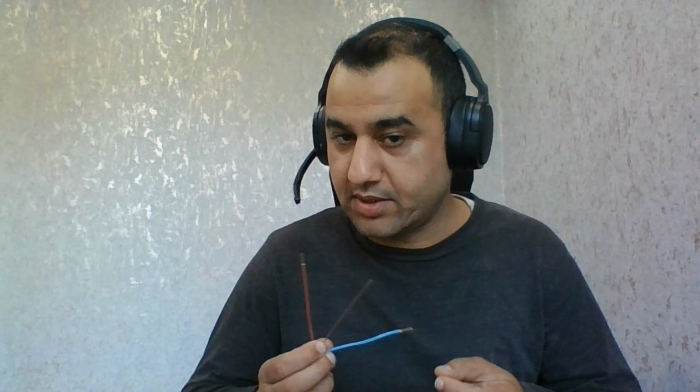So why do we have this third cable there? This is where a lot of people call it the safety cable, but how does it work? This is what we need to look into. It is a safety cable and it will protect you. It's called the CPC, circuit protective conductor. But we need to know how it is going to protect us, and why we need this circuit protective conductor alongside our phase conductors. These two are going to be your phase, the live, or line, and the neutral.